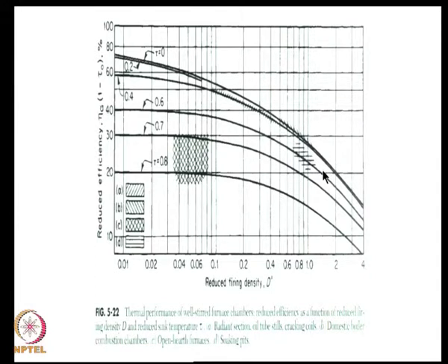So, it gives you a very good handle on the important design issues that we are dealing with, and as the cost of fuel goes on increasing and we need to make the furnaces more efficient, it shows clearly there is only one important way you can increase efficiency, by reducing the firing rate. We have not much control over the non-dimensional sink temperature, because that is determined by the application. So, in some application the sink temperature will be quite high, in others it will be low.